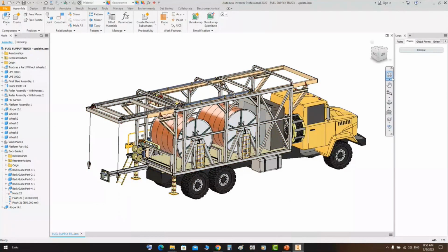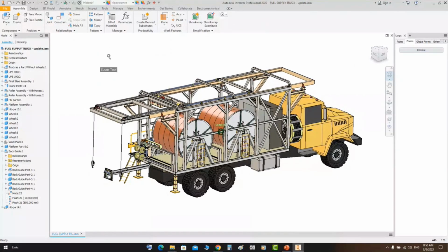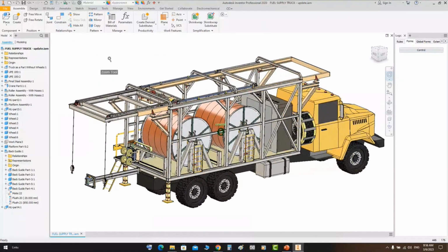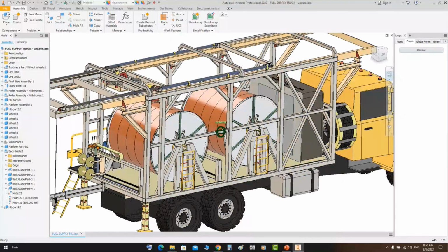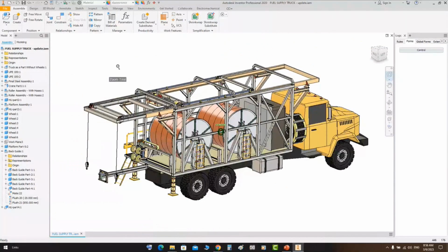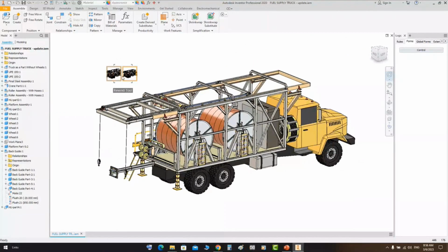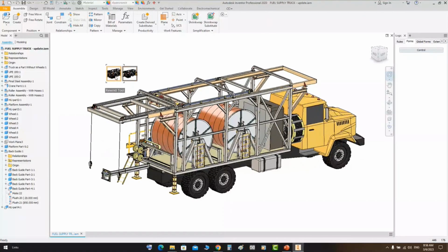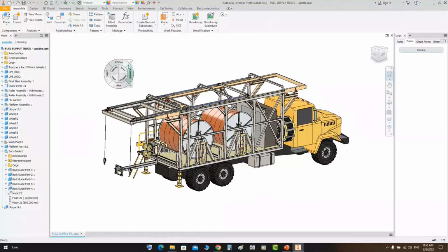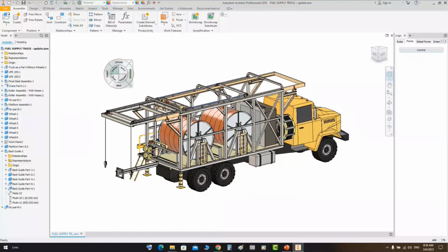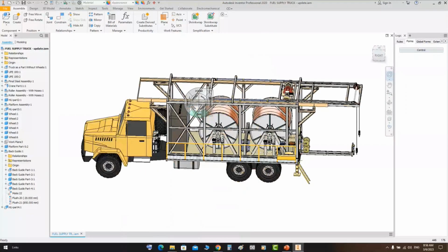If you click on the navigation wheel, you will get this navigation wheel here. It moves with the mouse like that. If you click on zoom and drag, keep clicking on it, you can make a zoom like that. If you click on rewind, you can move between the previous old views. Let's change that a little bit by clicking orbit. You can move the view like that.